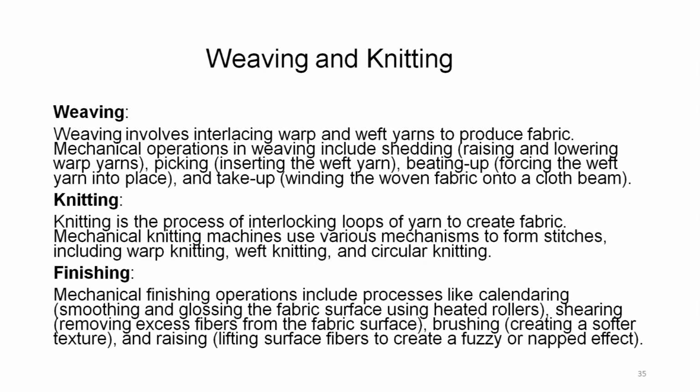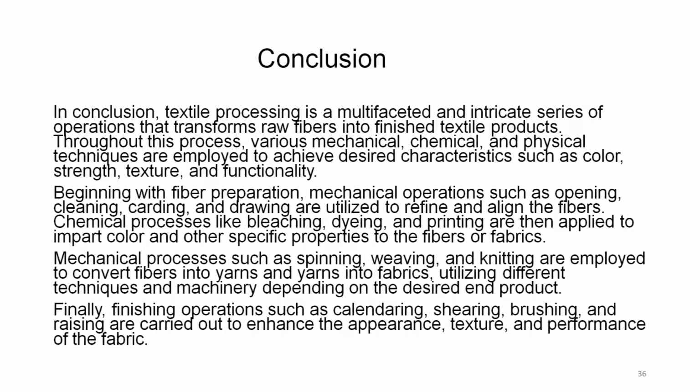Mechanical finishing not only uses calendering, which gives a smooth finishing and glossy look, but also it removes excess fiber from the fabric surface, brushing to remove all the fuzz that is created, the raising of the small bits of hair, and therefore, it is very important that these finishing processes are also done in the mechanical processing manner.